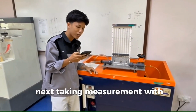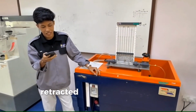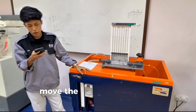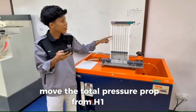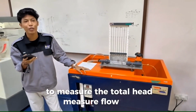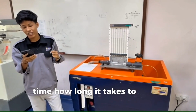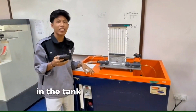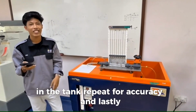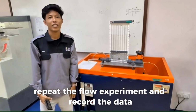Next, taking measurements with the water steady and the probe retracted, record the manometer readings. Move the total pressure probe from H1 to H6 to measure the total head. Measure the flow rate: time how long it takes to collect a known volume in the tank. Repeat for accuracy. And lastly, repeat the flow experiment and record the data. Thank you.